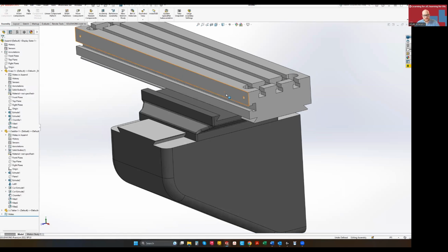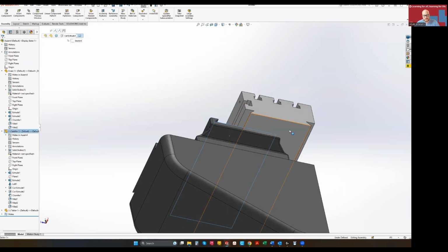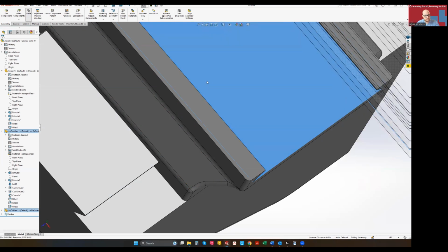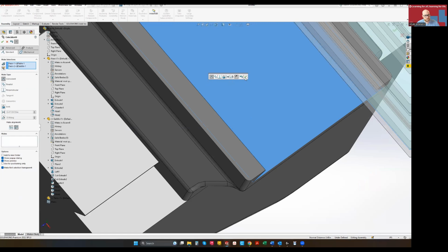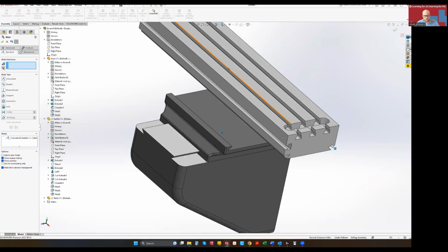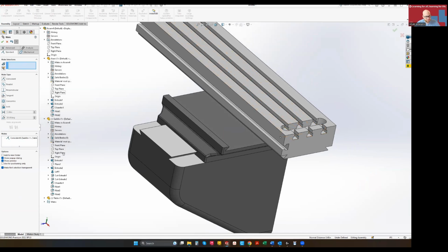And essentially it's just the exact same process that we just did. So we're going to make these coincident to each other, coincident to each other. Go ahead and grab that mate. Click the green check mark. Same thing as before, we can mate plane to plane here.